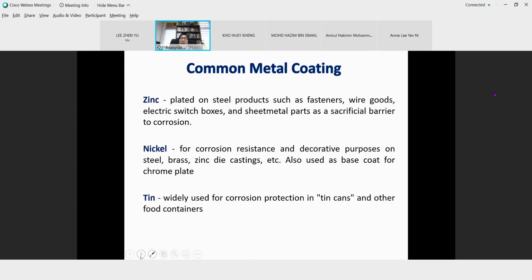Okay, let's say aluminium, it also depends on the material's environment. For example, if aluminium is in the air, aluminium will not be reactive, right? So that's why reactivity actually depends on the environment. Aluminium in air doesn't react, it doesn't deteriorate. It will form another structure, but it's not deteriorating. But when it comes to an acidic environment, it will be dissolved. When it dissolves, it means that the material will deteriorate, so it will reduce.